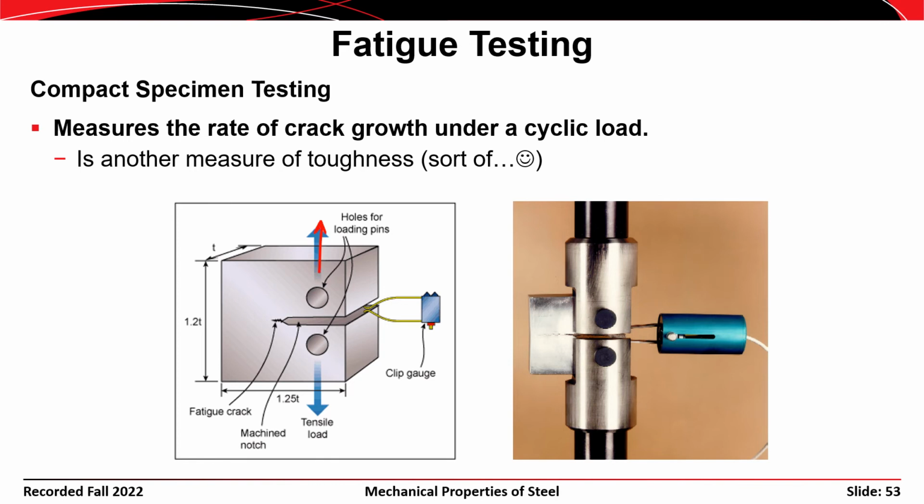And then the test machine just imposes a cyclic tension that ultimately leads to a fatigue crack. And the fatigue crack is outlined here. It basically starts there at the point of concentrated stress. And that crack actually develops and grows from right to left in the screen.